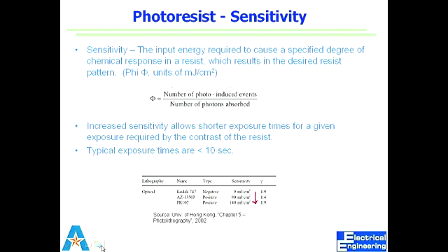So there's less light traveling away from where it's supposed to be. This is a figure of merit which is different for different resists, and the sensitivity, the gamma value, also changes with that. So with sensitivity, your contrast also changes, right? Increased sensitivity would allow shorter exposure, which means less dose, right? And we can get exposure done in less than 10 seconds.